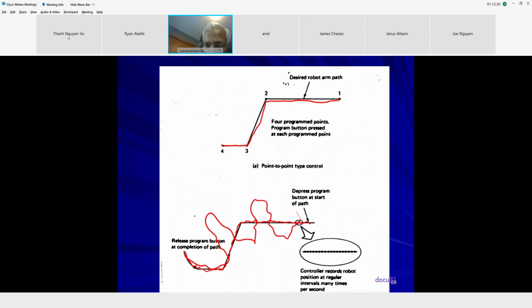You want it? You record at a high speed all the motion data points and make it reproduce. So this is a magnified section of many points stored in this little. So you are going to have millions and billions of points stored depending on the complexity. So in a continuous path, you simply drag the robot from one position to another position with a desired path and let it store enormous amount of data points.